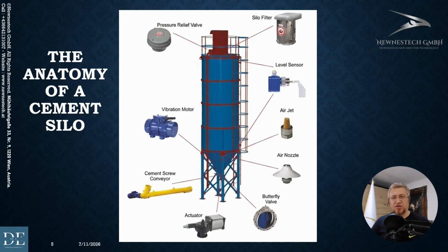The entire structure is supported by 4 robust structural legs. These legs are securely welded to the base plate, which will be anchored into a concrete mat foundation pad in our final design. To maximize structural integrity against wind, seismic, or lateral shear loads, these legs are structurally tied together with cross bracings. We will dive deep into the calculations and the structural detailings of these elements in upcoming episodes.